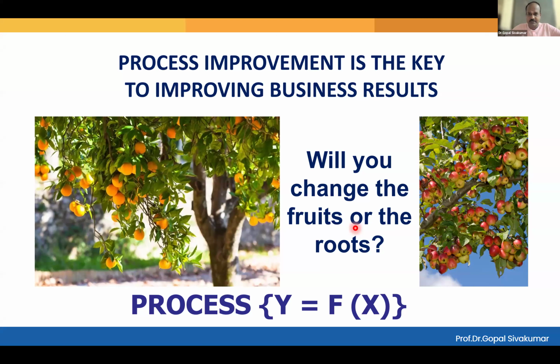But for the current problem, we normally get a particular amount of compressive strength, and all of a sudden in a particular batch, the strength has dropped. Now, which particular ingredient has gone wrong? That particular ingredient is the culprit. Yes or no? Suppose water is not added in proper quantity, then that is the culprit. Suppose cement is not added in proper quantity, that is the culprit. Suppose both the cement as well as water are not added in the right quantity, there are two culprits now. Can you see that? Yes.